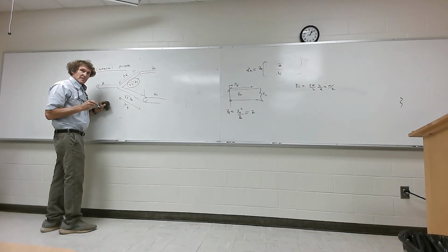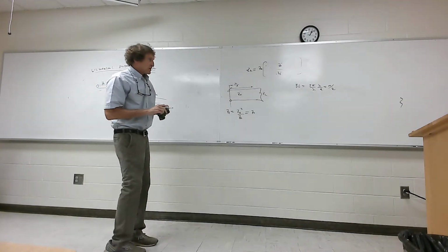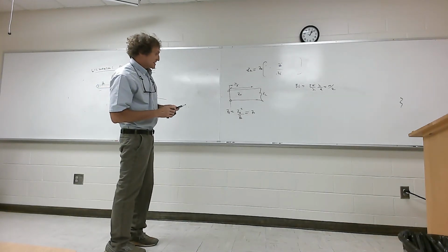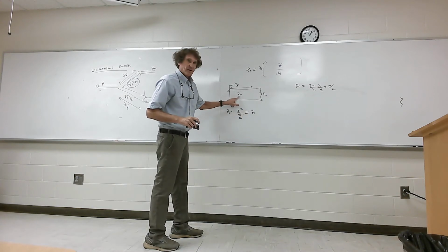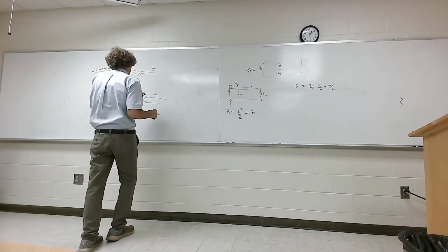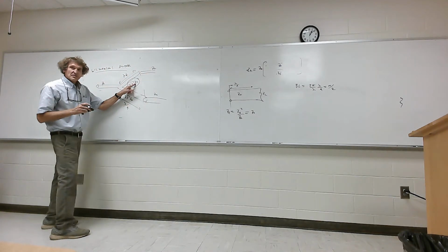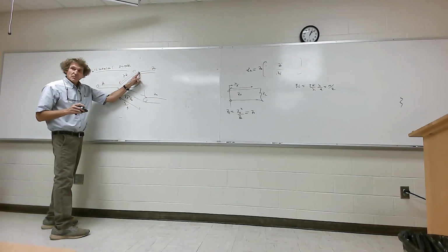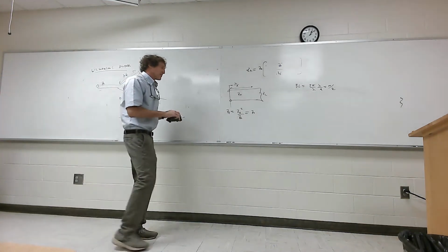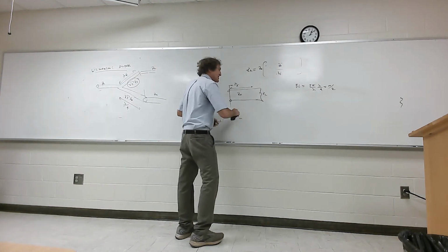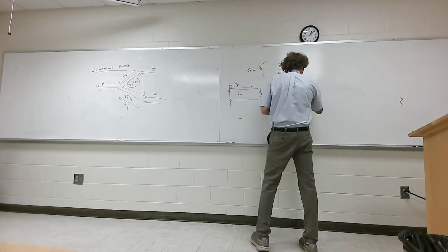Well, I didn't do this very well, but I should have basically said that this characteristic impedance is the characteristic impedance of the transmission line. That characteristic impedance of the transmission line is actually square root 2Z naught for this quarter wave portion, and the load is Z naught. So really, you're going to have square root 2. Just hold on, I'm not saying this very well. Let me redo this because I feel bad.